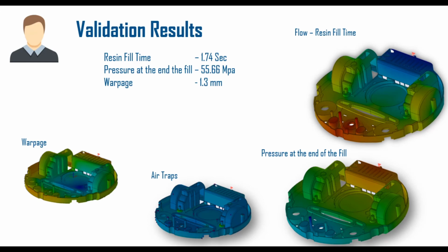So total fill time is 1.74, pressure at the end is 56, and the warpage is 1.3. So we are all set. From this we could conclude there are no defects with the plastics. We could directly take this one into account